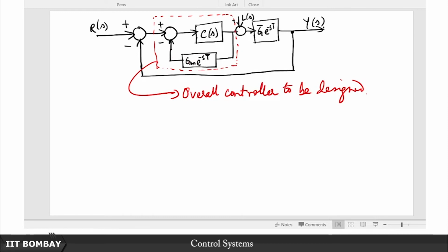So remember, this GM is depending on how well I have modeled G bar, this T bar is depending on how well I have modeled T, okay. So this is the plant, okay. So this part is kind of fixed by my estimation capabilities, and this part is where I choose whether I am designing a P or a PI or a PID controller, right. So that is basically the goal.